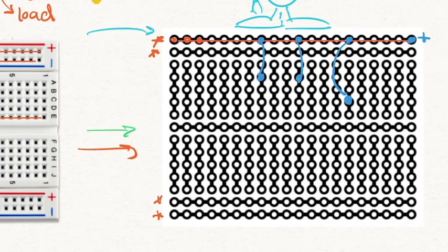Looking inward now, we see that the holes are connected perpendicularly to the power rails. So we have them connected like this, whereas the power rails are connected horizontally. Now, why is this advantageous? Well, say you bring a wire from here, like I drew earlier, to right here, and then you want to attach a load somewhere here. Let's say it's an LED. Well, one leg of the LED will be here, and the other leg of the LED will be here, so it'll be mounted like this.